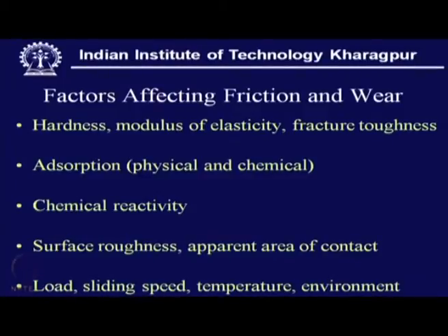And then comes load. These are the external inputs, that means the normal load under which these two parts are working, then comes the sliding speed, then temperature and environment. Environment means if it is a humid atmosphere or dry atmosphere, if it is an oxygen rich atmosphere, or it is under normal vacuum, or if it is under ultra high vacuum.